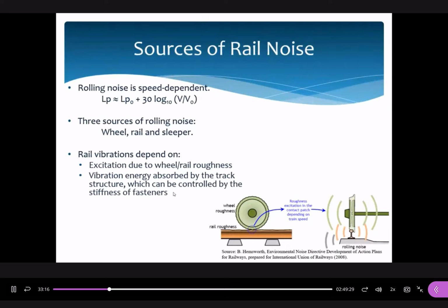Ground-borne noise is a kind of structure-borne noise when a train moves inside a tunnel like this one. Because of the vibration effects, the low frequency vibrations can be transmitted through the connected structures to the nearby building. And inside the buildings, it could re-radiate low frequency noise to interior areas. It is so annoying. The low frequency noise should be in the range of 30 to 250 hertz.